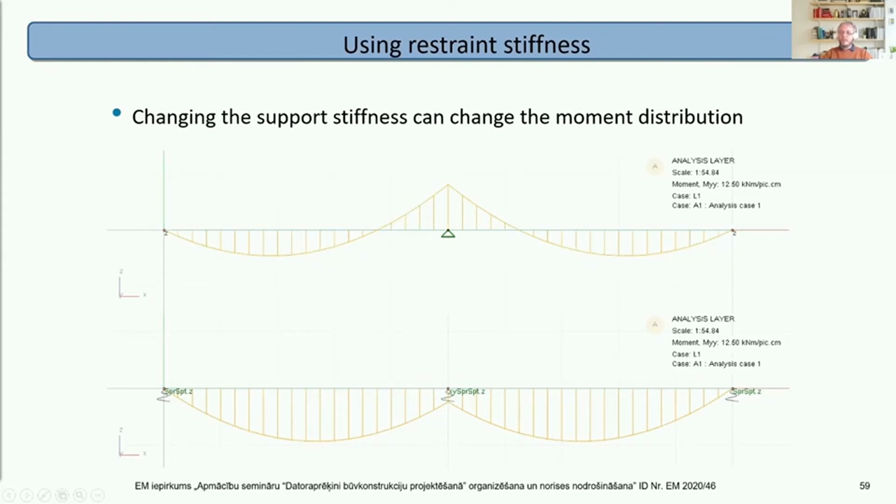What you don't see in this diagram is just how much this beam is deflecting. It is going down quite a long way to give these results. So I think lateral torsional buckling was not your problem, more serviceability problems of people bumping their heads on the ceiling is more of a problem for this model, or just sliding down the middle.